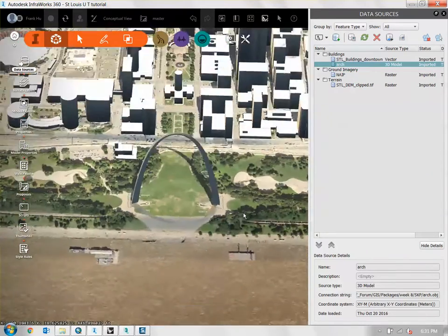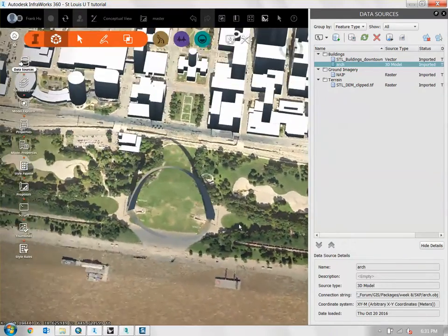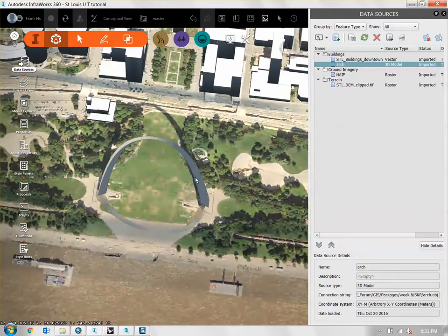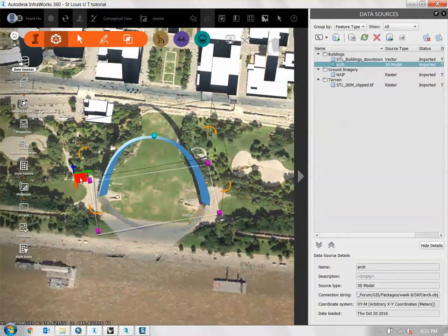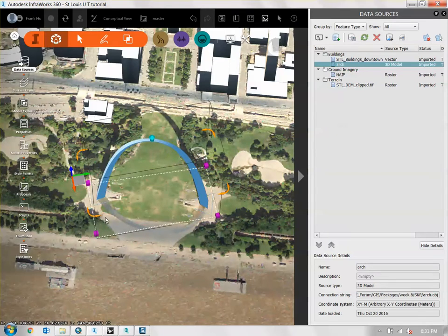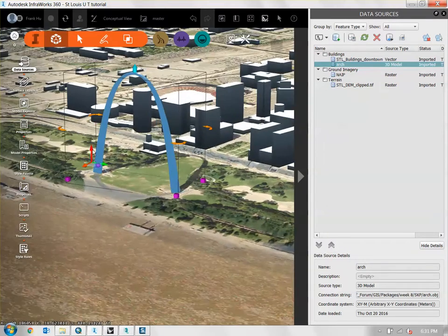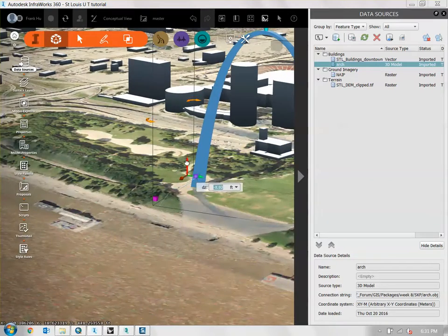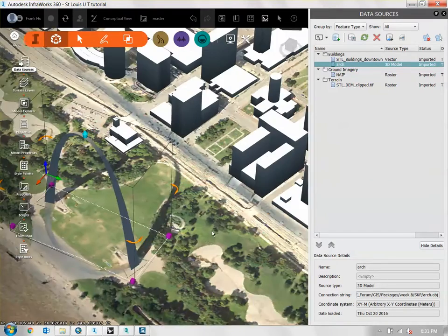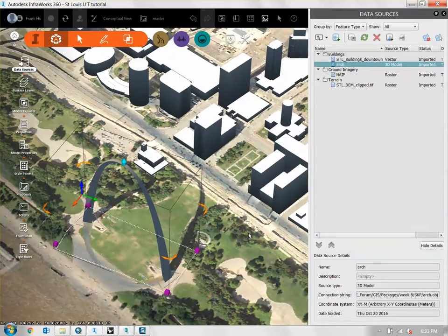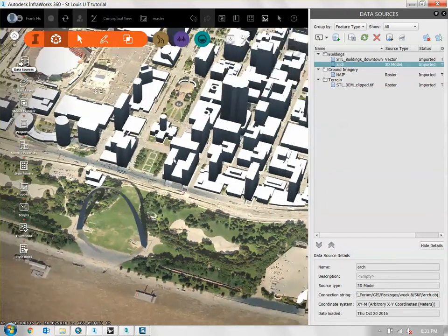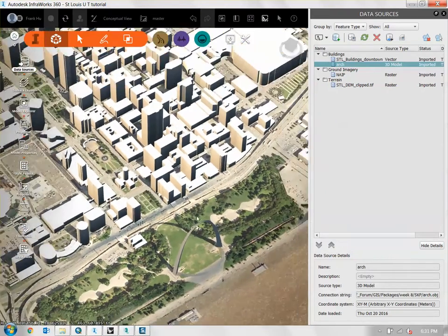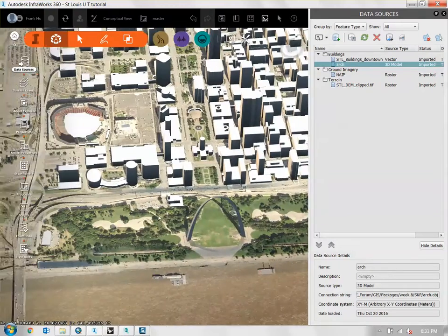And so that's how you put custom architecture onto your building. And then you can click on the building and manually adjust it using the gumball tool or the move tool here, just to set it and rotate it to fit the site. You can also move it down a little bit. So this is basically how you begin to resolve some of the places where the buildings don't look realistic, but you have a 3D model of, say, a building that looks realistic. That's how you fix that problem.